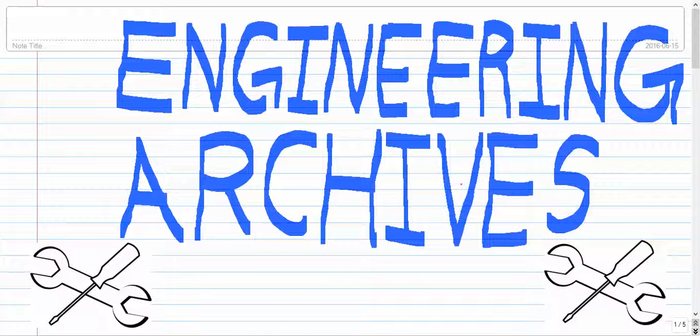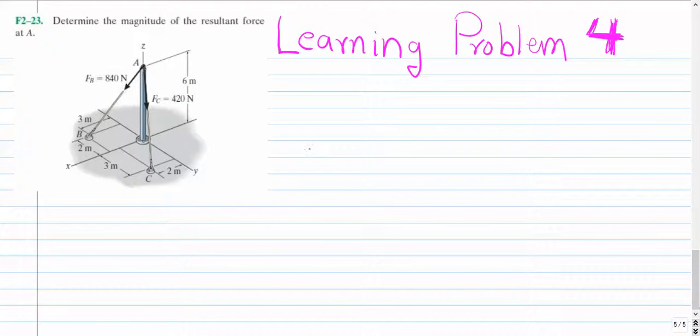Let us look at learning problem number 4 for the chapter force vectors. So this question says, determine the magnitude of the resultant force at A. So we have two force vectors, FAB and FAC, and they want us to add both of them and give them the magnitude of the resultant vector. So in order to solve this question, we'll first have to find the Cartesian forms of both FAC and FAB. Once we have their Cartesian forms, we can add them, and after that we can use the resultant force formula to find their resultant magnitude.